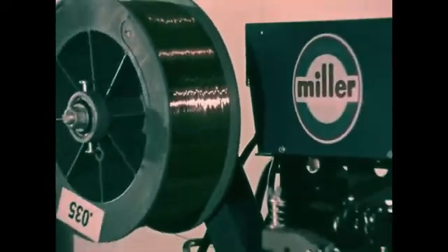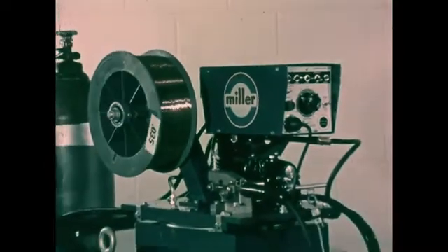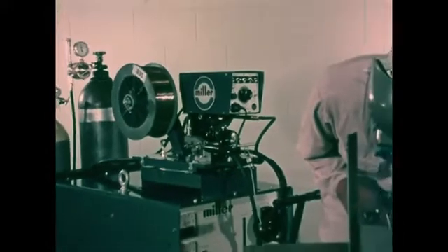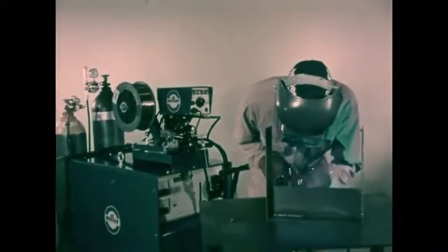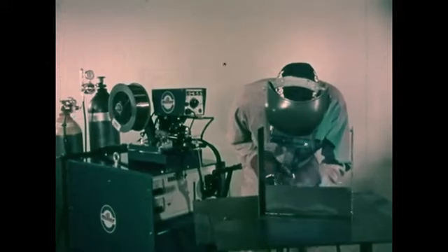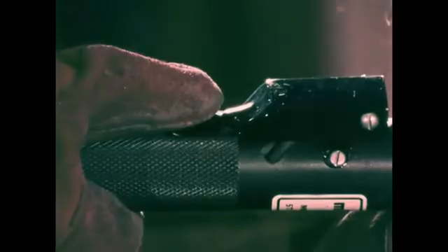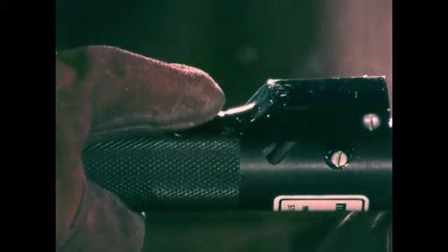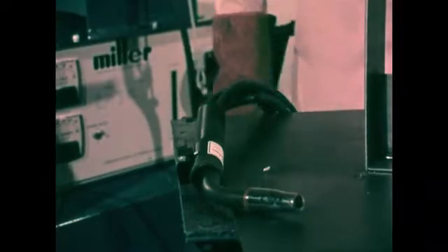The spool of wire electrode permits continuous welding without the need to stop and start frequently. It is obvious that this method of welding is one of the easiest to use. It is relatively clean. The wire is not electrically energized until the operator depresses the trigger on the top of the gun, and of course is de-energized when the trigger is released. A very safe procedure. The short-circuiting method operates at controlled low voltage and amperage when compared with other methods used within the gas metal arc welding process.